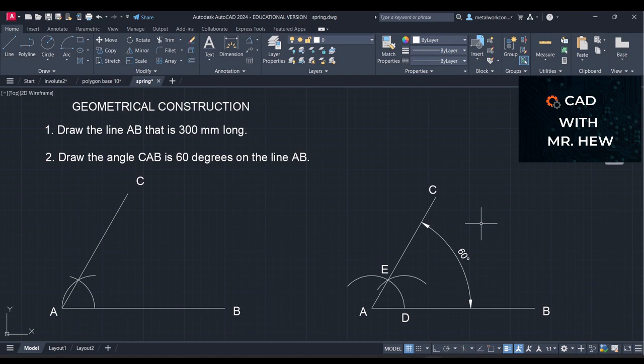So whether you have math or technical drawing, it is the same fundamental principle used to construct a 60-degree angle using your geometry set instruments, right? So in today's video, we looked at how you construct a 60-degree angle using the geometry set compass or in AutoCAD, right? And it's a fundamental construction, as we said, using math and in physics. If you're doing a forces diagram, and you're doing it graphically, meaning maybe on graph paper or on folder paper with a geometry set, you could use this method.